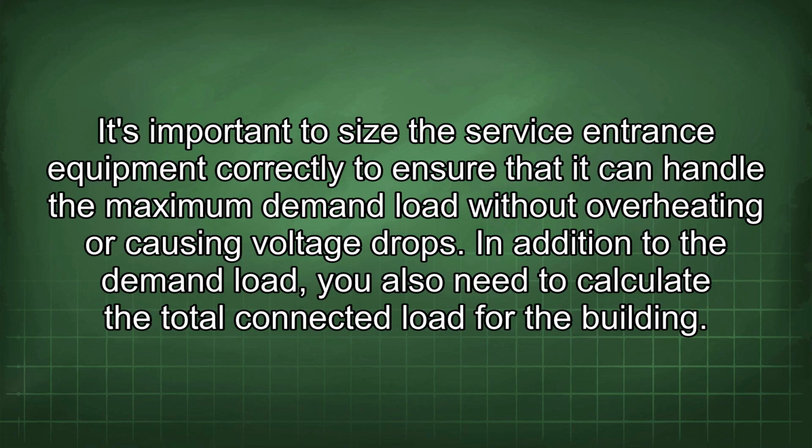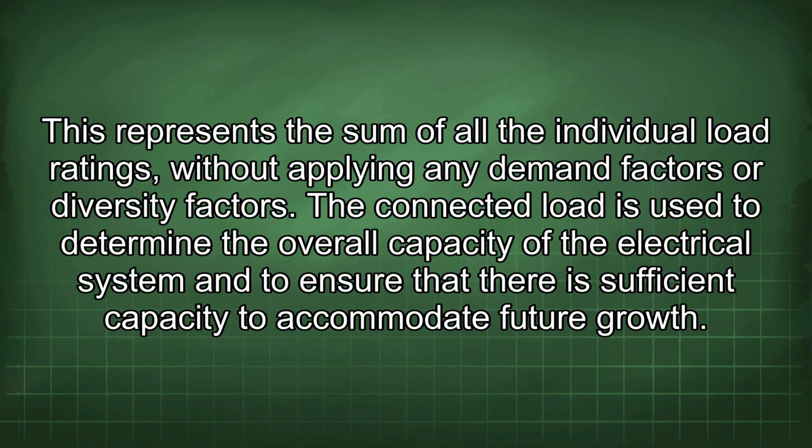In addition to the demand load, you also need to calculate the total connected load for the building. This represents the sum of all the individual load ratings without applying any demand factors or diversity factors. The connected load is used to determine the overall capacity of the electrical system and to ensure that there is sufficient capacity to accommodate future growth.